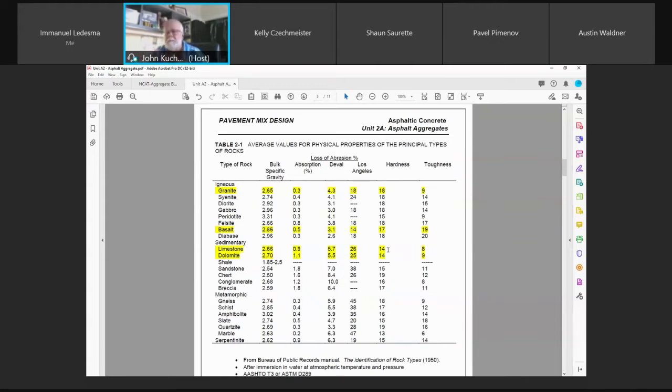Whereas if I have a cubical, maybe a pit run aggregate, there's some crush in it from the processing. Okay, I'm taking larger pit run cobbles and I'm crushing them down, say, so I get 100% passing my 16 millimeter. I've got my angular, I've got my crush count, I met that. But they're not going to wear down as much as all the sharp edges on a crushed aggregate. So a lot of people figure, oh, I'm going to use granite, my LA abrasion is going to pass. Not necessarily. So this is a good indication here.